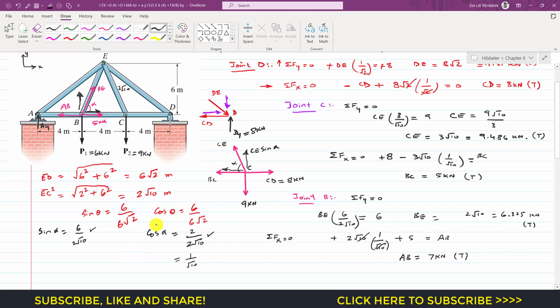So now ultimately we reach joint A, so again we need to consider the forces at joint A as well. Now let me draw the free body diagram at joint A. So let's say this is that joint A, and at joint A the AB force will be acting away from that joint A, since the AB force is the tension force, so it will be acting like this.